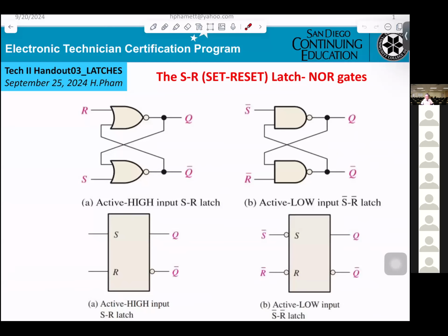So what I was saying, Mr. Pham, is when you have that situation, you get another person's hardware and test your program against their hardware and vice versa. Well, yeah, I would first test my board. If someone's board is the same and it's working already, you can run your program to test on that. If it passes, that means your software is okay. Now you know your hardware has a problem. Just one by one.